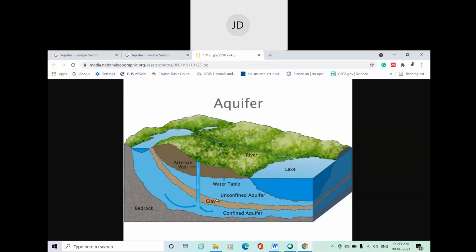Okay, that means from this side you can say the water is blocked. That's why it's called an unconfined aquifer. Now, when it comes to this soil, this water layer, which is the confined aquifer, it is noted here. So below this layer, what is it? Bedrock. Okay, bedrocks are there. And above this clay layer, water will not easily come in the upward direction or the downward direction. That's why it's called a confined aquifer. That is, it is confined from both directions. Water can travel along the lateral direction but should not go through this.